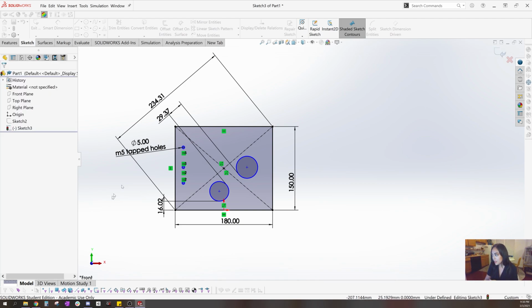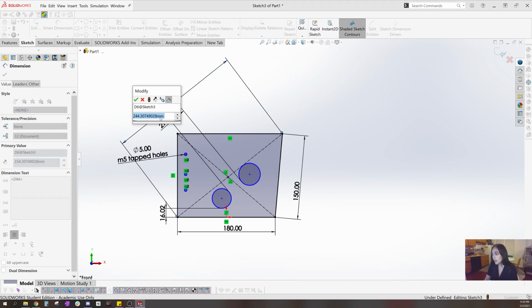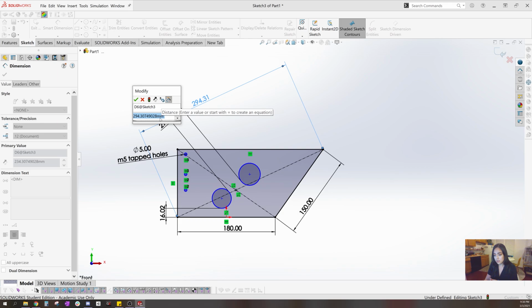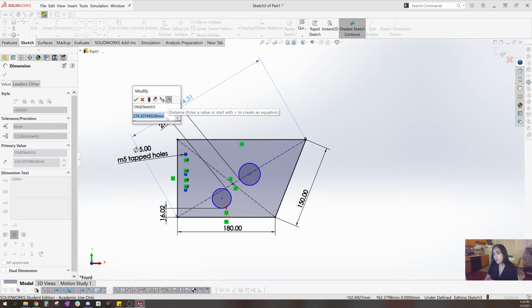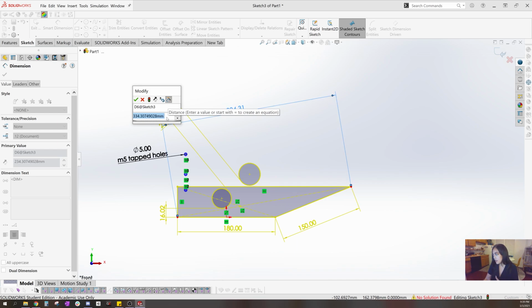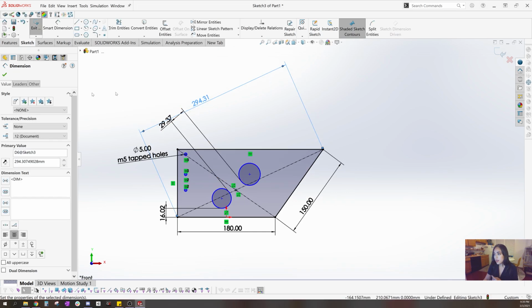The sketch is working. Because that vertical is gone, if we mess with this feature here, so I'm using the scroll wheel again to make it bigger, you can see how that changes and how deleting that vertical relation has changed the part here. Pretty cool stuff. There is a point, again, where SolidWorks will break if I continue to make this bigger and bigger. We can have SolidWorks try to fix this again, but right now it says no solution, so we really messed up. So I'm just going to backtrack this and say, okay, that is my final part there.